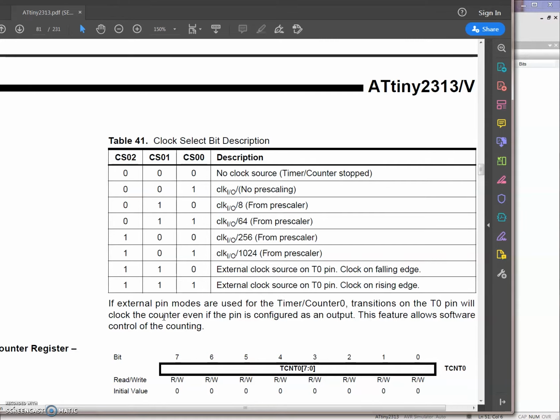And then it would have to reset back to 0. So we want a much higher value than 19 because 19 doesn't give us much resolution at all. So the next value option is 256. So if we take 20,000 and divide it by 256, we get 78.125. So we round it off to 78. So that's a possible option.